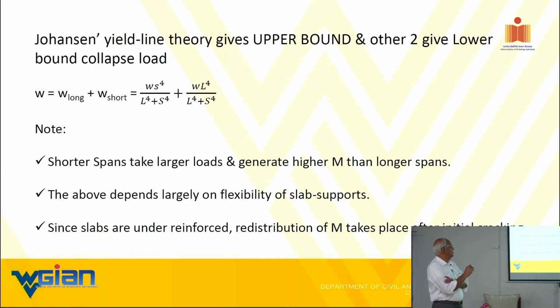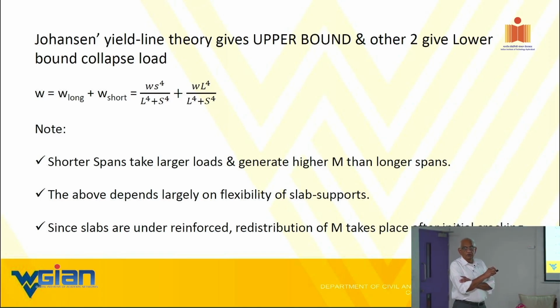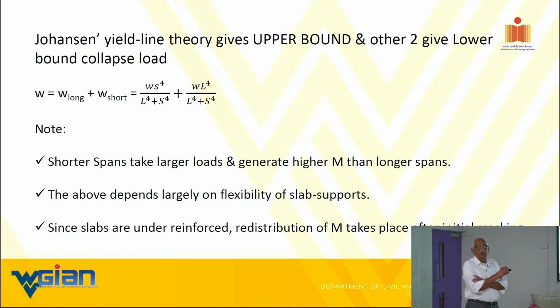So this morning I told you, if I have two beams, I'm talking about deflection on the long side, deflection on the short side, and that is, you remember your good old 5/384 WL^4 over EI?